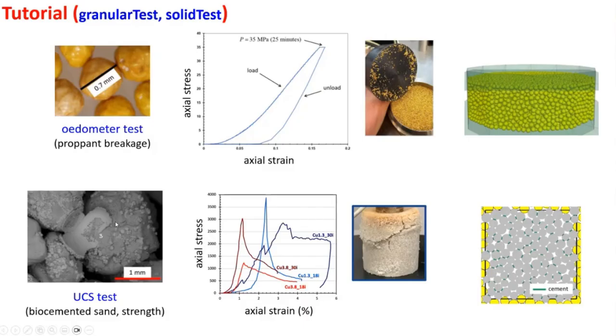And what they do is they take this dry sand, they put it into a cylinder under gravity loading, it sits there. Then they take a platen and they place a small load on this. They just put a big weight on there. So now it's all packed, because when you just drop it in there, it's very fluffy on top. So they pack it at some low pressure.